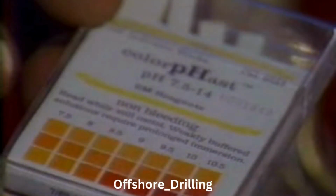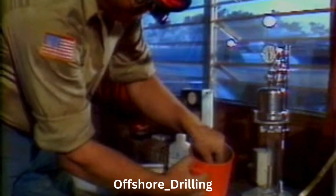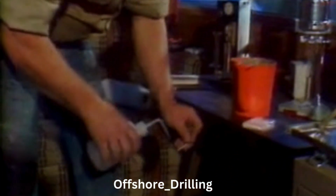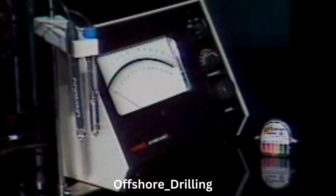The mud is also tested for its pH level with pH paper. At this point, I check the pH, and on this mud at this range, I'm trying to keep it between 9.0 and 9.5. I came up with a 9.0. This pH meter is used sometimes instead of pH paper.